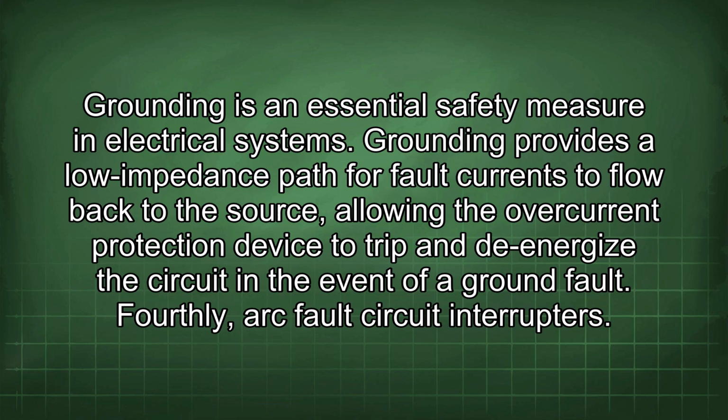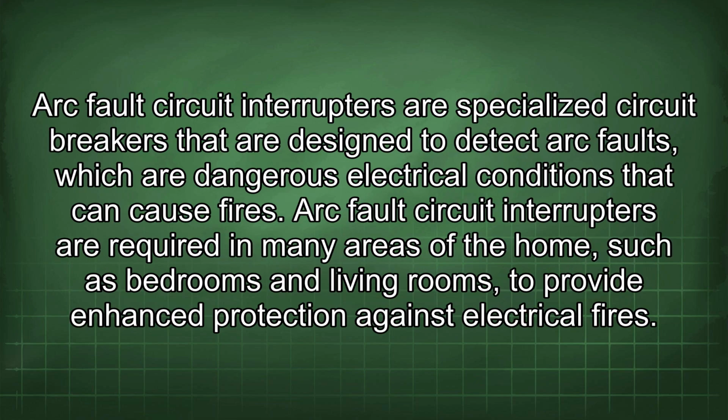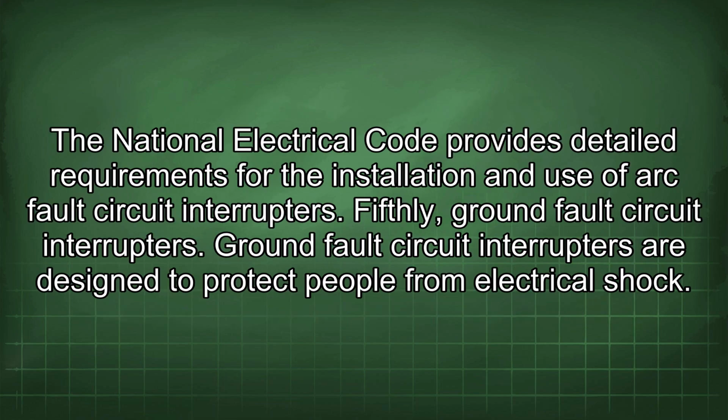Fourthly, arc fault circuit interrupters. Arc fault circuit interrupters are specialized circuit breakers that are designed to detect arc faults, which are dangerous electrical conditions that can cause fires. Arc fault circuit interrupters are required in many areas of the home, such as bedrooms and living rooms, to provide enhanced protection against electrical fires. The National Electrical Code provides detailed requirements for the installation and use of arc fault circuit interrupters.